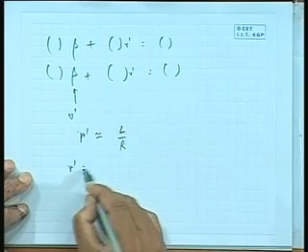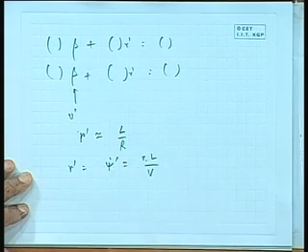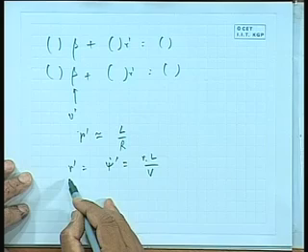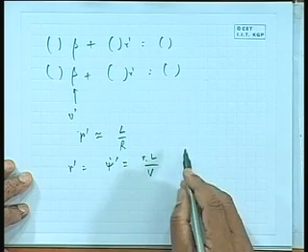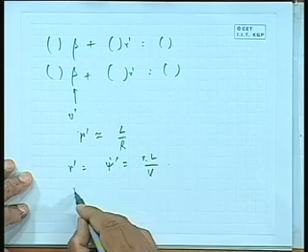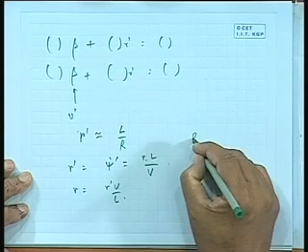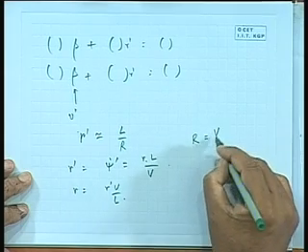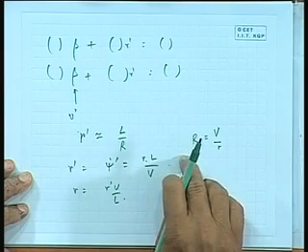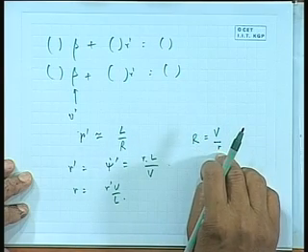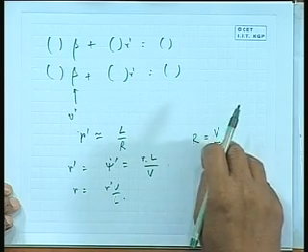R dash by definition is equal to psi dot dash, which is equal to r into L by V. If you look back at the non-dimensionalization, I had r dash defined as r L by V. That means r equals r dash V by L. Now r by definition is V by R, the steady turning radius, and by definition V equals R into r.